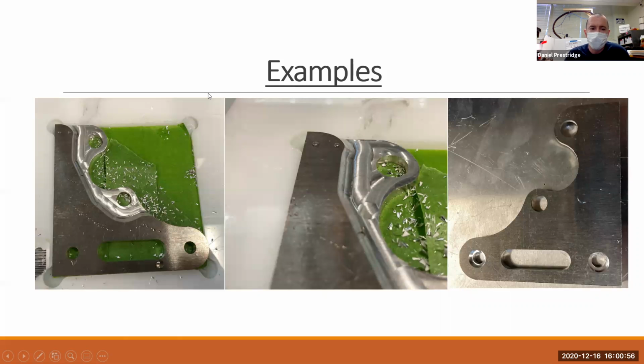So this follows along the same vein as they also wanted another part that was a little bit smaller. It had countersunk holes on the backside, and it had a pocket here to clear that material because they had to fit this onto, I think, a brake caliper. And then they wanted to fillet it too, because if you don't add the fillet, there's a thing called stress concentration that can lead to failure, premature failure. So they needed to have that transition curving downwards into the part.